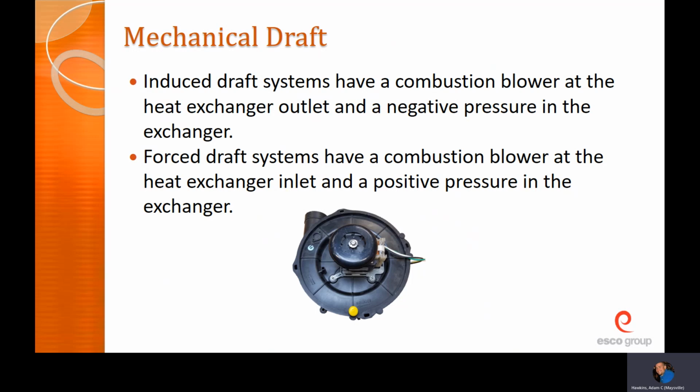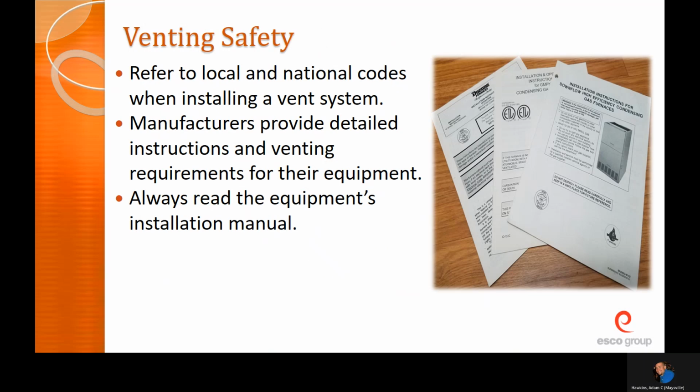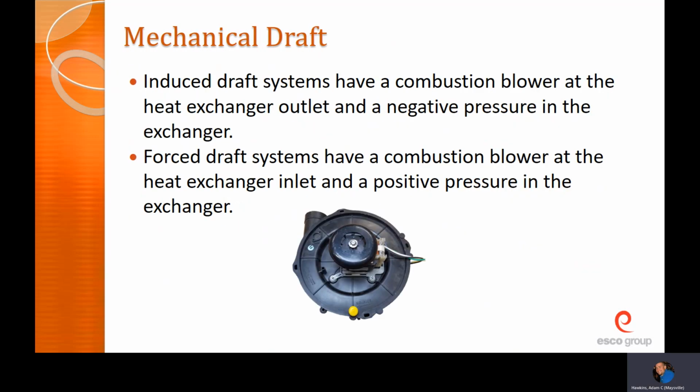And so you may think, well, what's the big difference? Why would they do one versus the other? There are a few different theories on that. The main one I can think of, and that I've heard, is that induced draft tends to be the way it's done because if you had a leak, a cracked exchanger, a hole in your exchanger of some sort, with a negative draft system you're more likely to pull in air from around it, your return air, your house air going through your furnace.